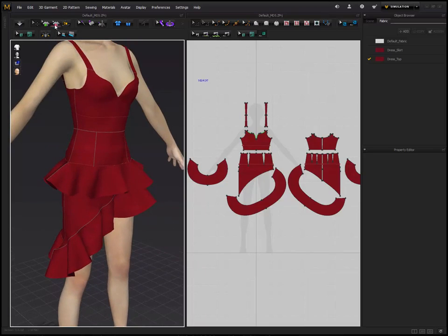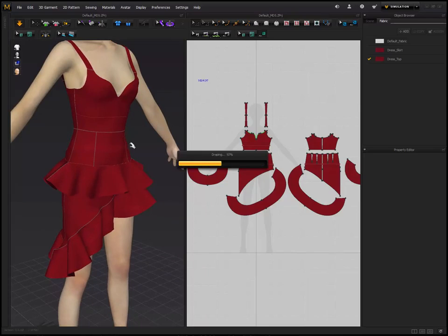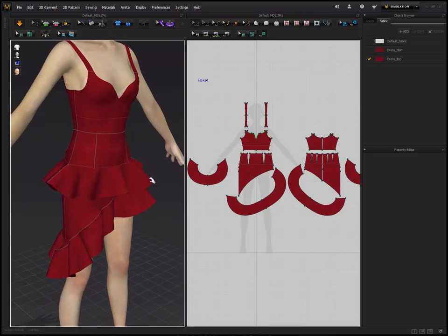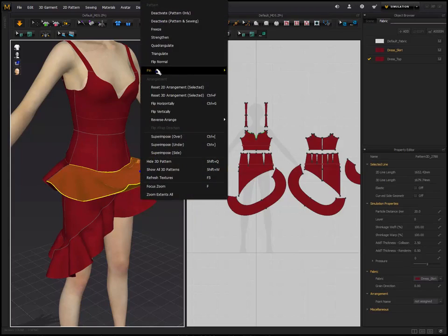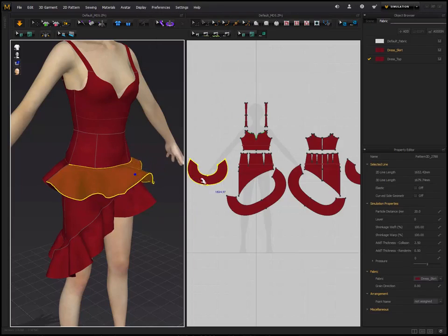First, to create any pin on the map without selecting this, as long as you're selecting on the basic tool, if you're in simulation mode, left click and hold, you can create a pin. It'll be this orange pin. You create as many of these as you want, and you could always delete them by holding W and left clicking it, it'll delete the pins also. You could also create multiple pins. They're great for temporary holding stuff in place, fix errors, and anything like that. You could also select on this mesh, right click it, and you could go to pin and delete all pins. It'll delete all the pins on the mesh.